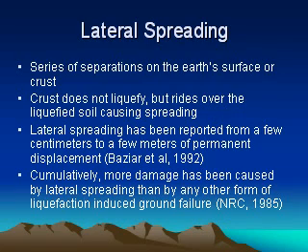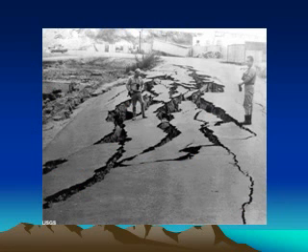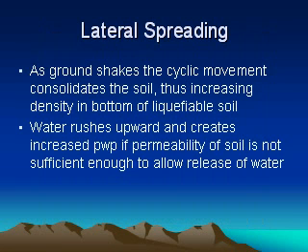Lateral spreading has been reported from anywhere from a few centimeters to a few meters of permanent displacement, and cumulatively more damage has been caused by lateral spreading than by any other form of liquefaction-induced failure. Here's a picture of a lateral spreading that occurred near a bank. As you can see, the wide spreads that are possible in lateral spreading.